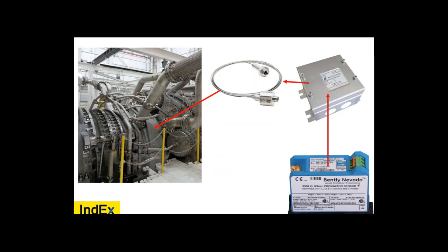Now I'll answer people's questions that they've proposed. Can we do self-declaration for EX nA and EX ec control panels without an ATEX certificate? Okay, that question's all over the place. nA panel, you could, if all of your internal components and the panel were manufactured before a certain date, let's say some date in 2018, and you assembled it. Then as a manufacturer, you can self-declare, declaration of conformity.